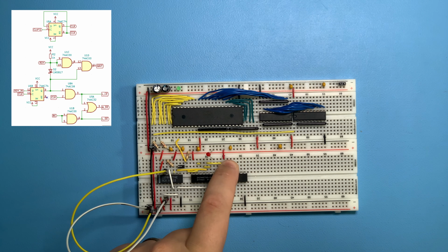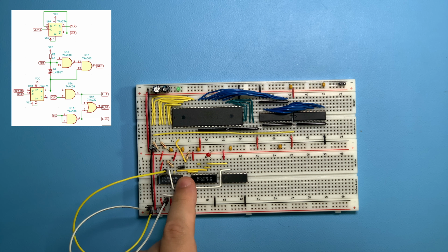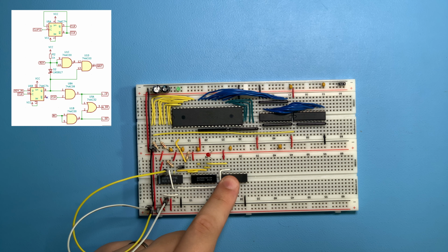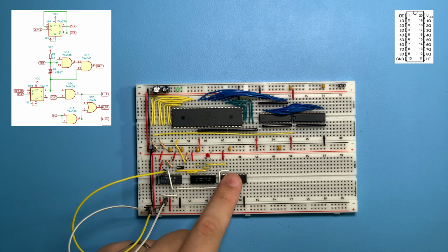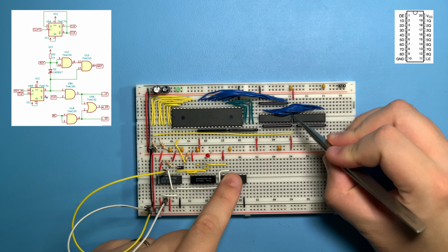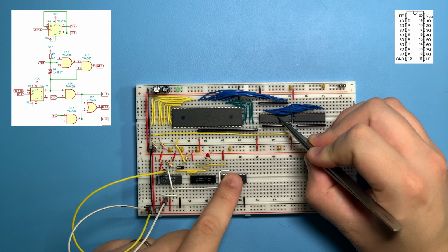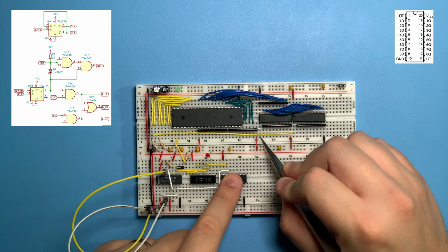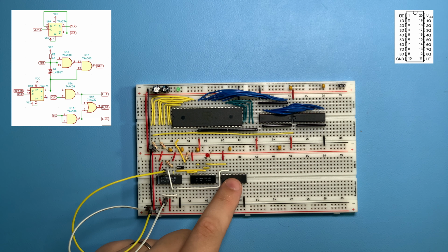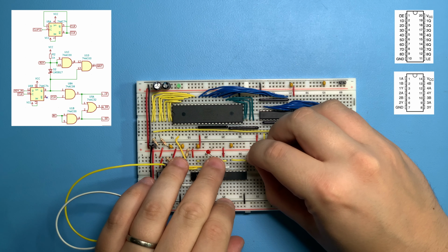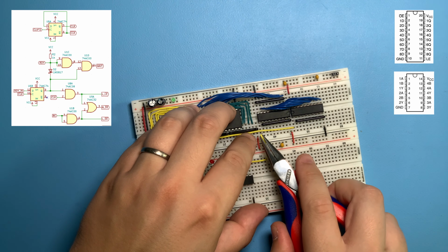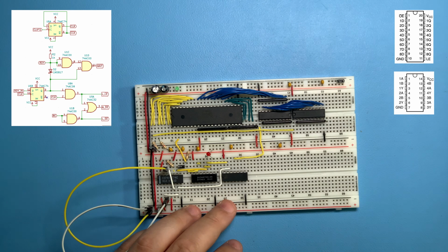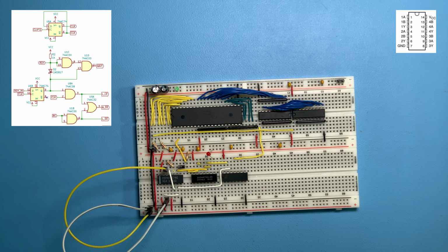So from the AND gate of the inverted clock and the clocked ready pin, we go to the latch enable of the latch. And so that's going to be pin 11 on the latch. And we have to remember that the latch is the other way around. The pin here. Okay, so this is our latch enable signal.